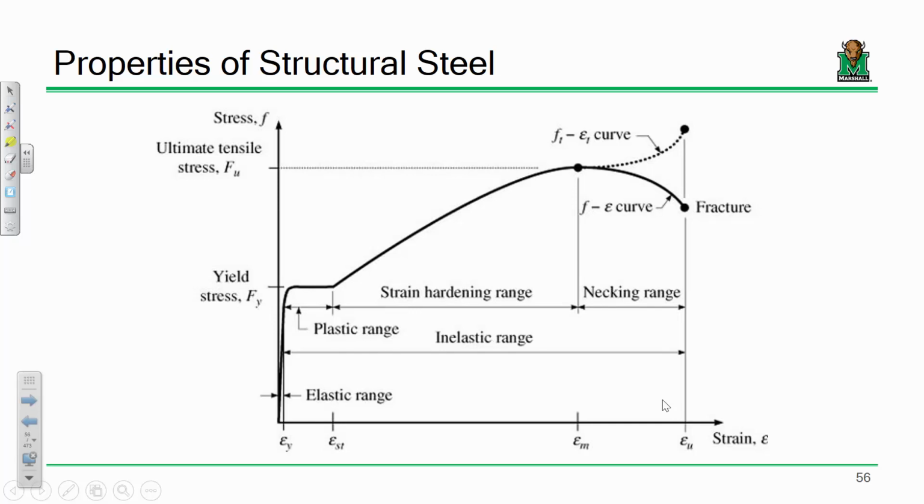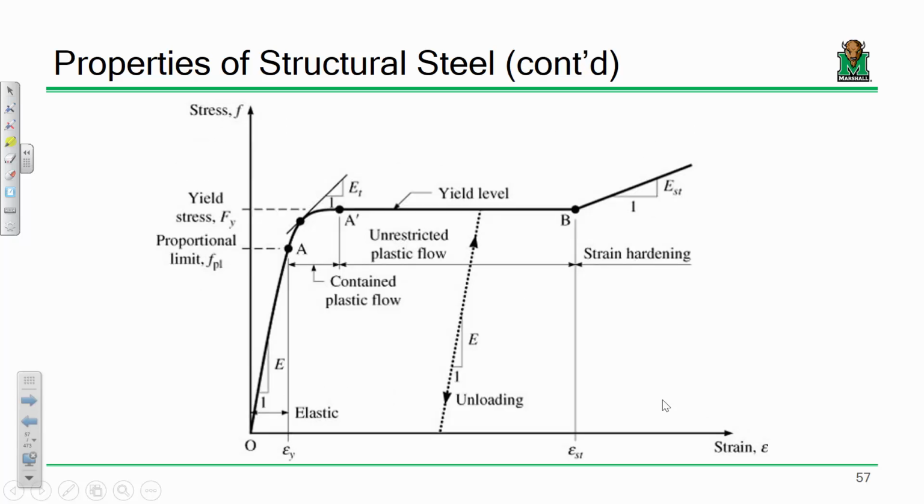From here to here, that's about the 10-yard line. So that's that perfectly plastic behavior where it just freely deforms until it catches up and it starts to strain harden. That's the other end zone. That's the whole other end, to give you kind of some scale. So steel has a really remarkable ability to withstand some very significant inelastic deformations. It's an extraordinarily ductile material, which makes it a material of choice when you have significant inelastic demand, like in earthquakes and things like that, as long as you're doing your detailing appropriately.